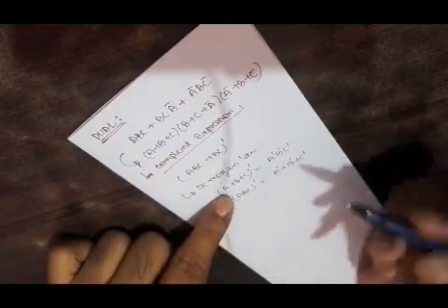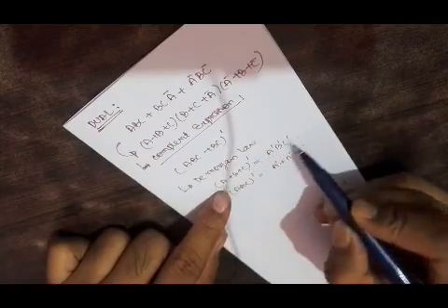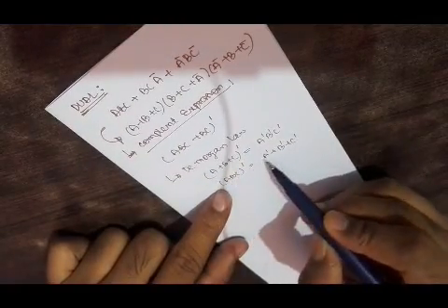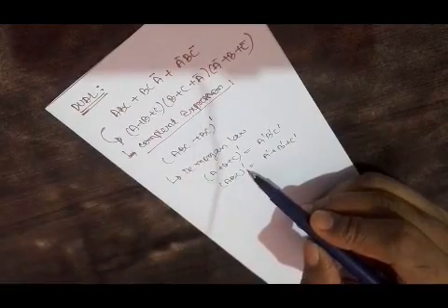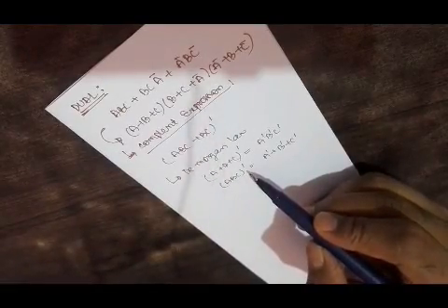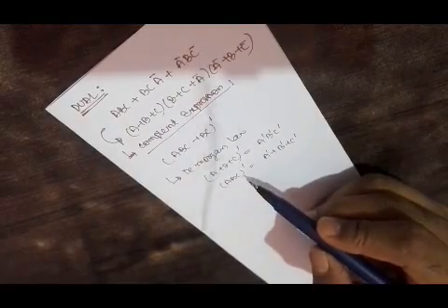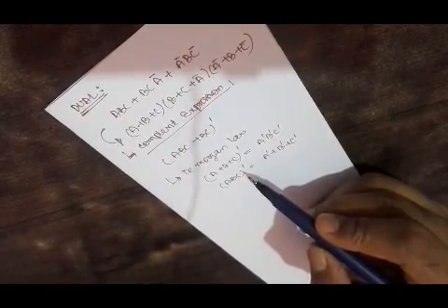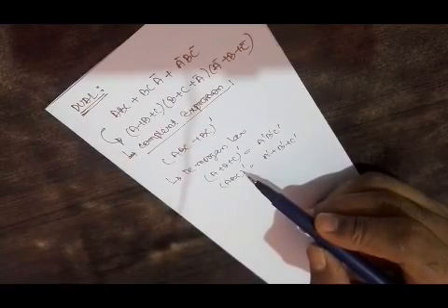So it is dual plus complement of each term. ABC we are converting into OR, but with a complement of each term. Again, the ABC product we are converting into the OR form, A plus B plus C, with a complement of each term. So it is both. We are doing it dual and with the complement of each term, right? So this is De Morgan's law. Then we have positive logic and negative logic.